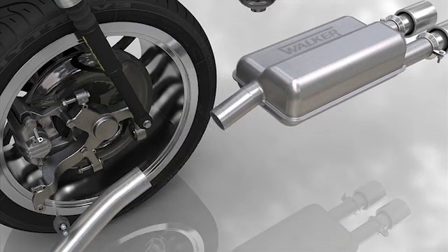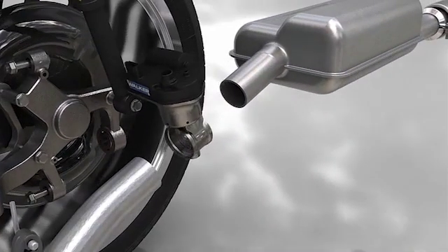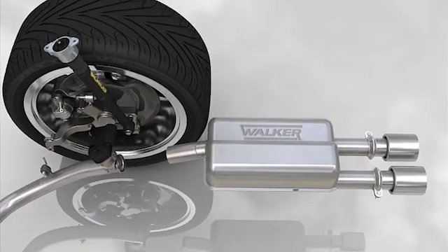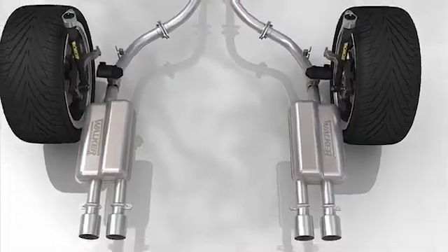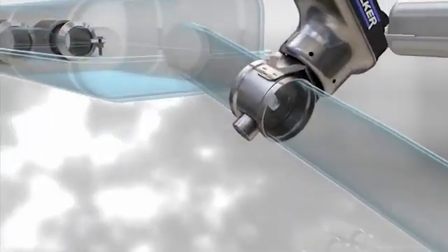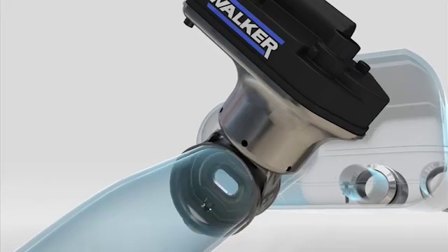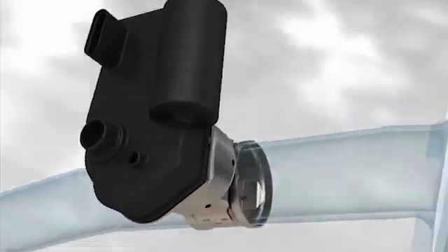Its operation is very simple. This electronic valve is integrated in the car's exhaust pipe before the rear silencer. The valve is controlled by the car's electronic control unit, ECU. Inside, the valve contains a disc with a central bore rotating on its vertical axis. On turning, the disc opens or closes the flow of exhaust gases, increasing or decreasing the level of back pressure.